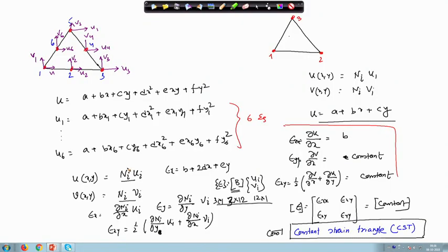You take any arbitrary point and sum all the shape functions, and see whether they give you 1 or not. These are properties that shape functions must satisfy. By construction it should, but when you write a code, these are checks you should perform to verify whether the code is written properly or not.